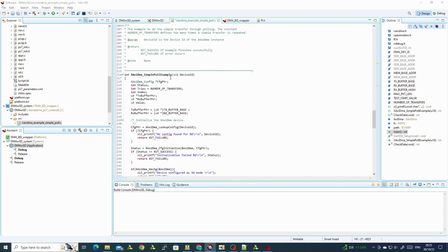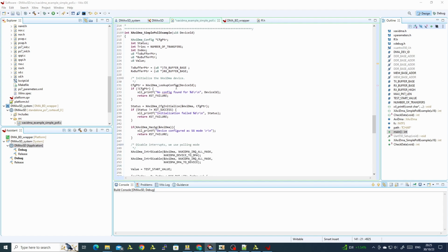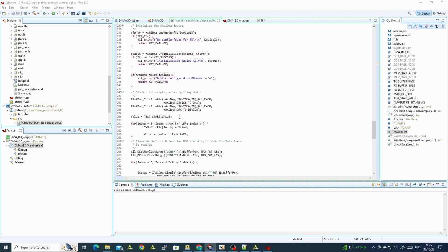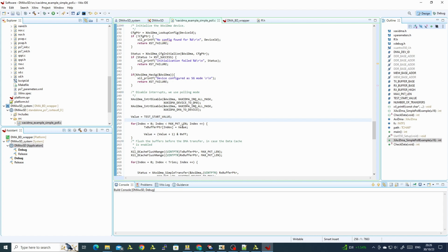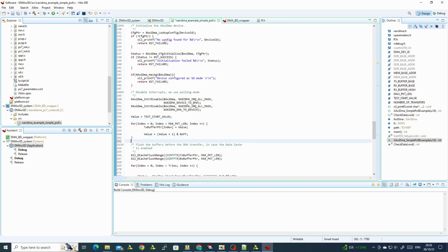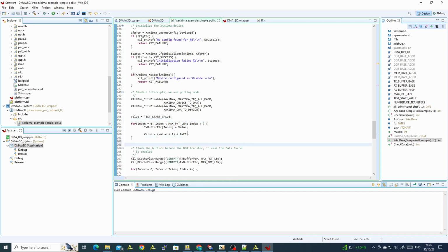Now here at the start is the DMA configuration. We went over this in my DMA tutorial. I'll skip right to here, which is the generation of the data. We generated the data as a simple counter, and this is the data we used in the DMA tutorial. Now after this, I want to read from my SD card and overwrite the data generated by this software.